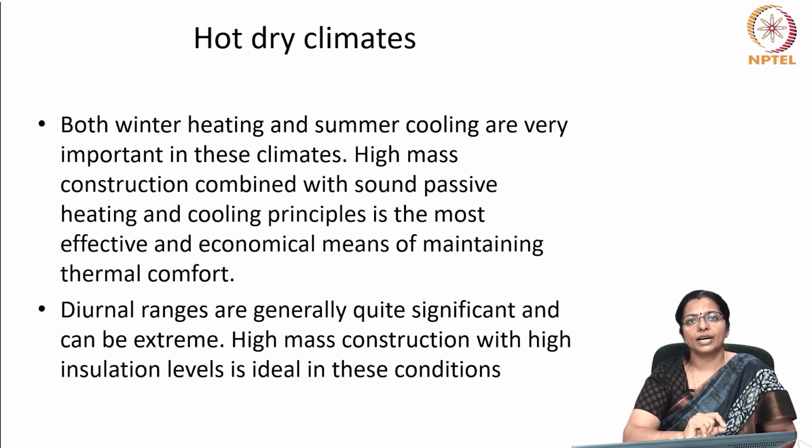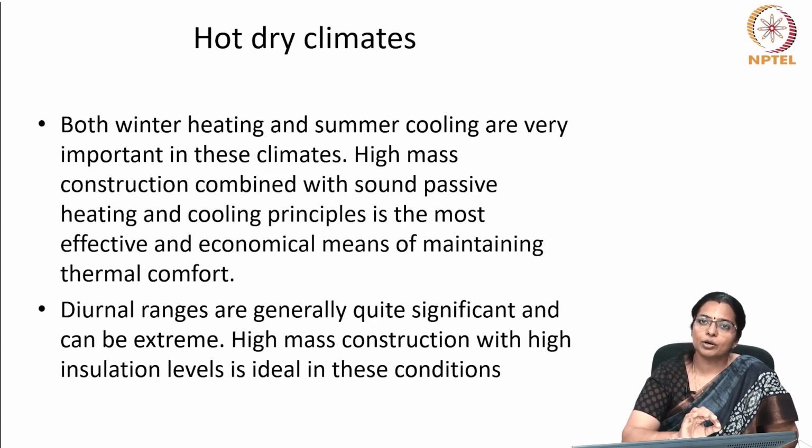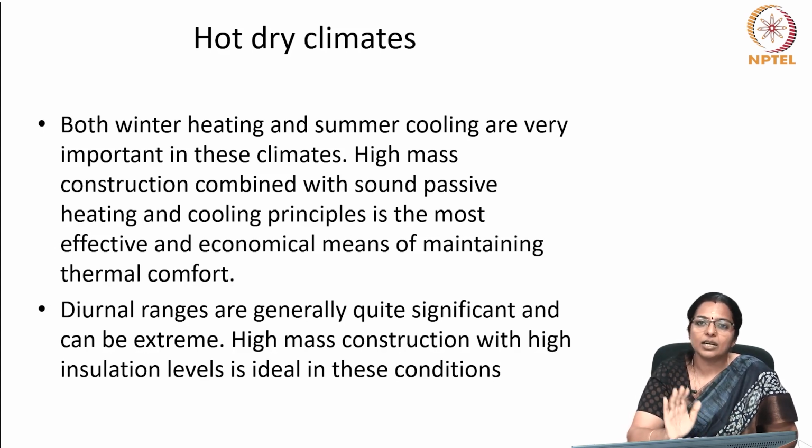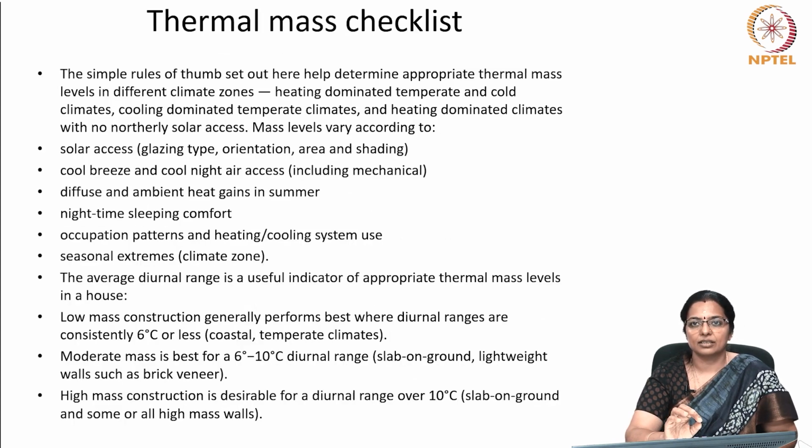What happens in hot, dry climate? Both winter heating and summer cooling are very important in these climates. High mass construction combined with sound passive heating and cooling principles is the most effective and economical means of maintaining thermal comfort. Diurnal ranges are generally quite significant and can be extreme. High mass construction with high insulation levels is ideal in these conditions.